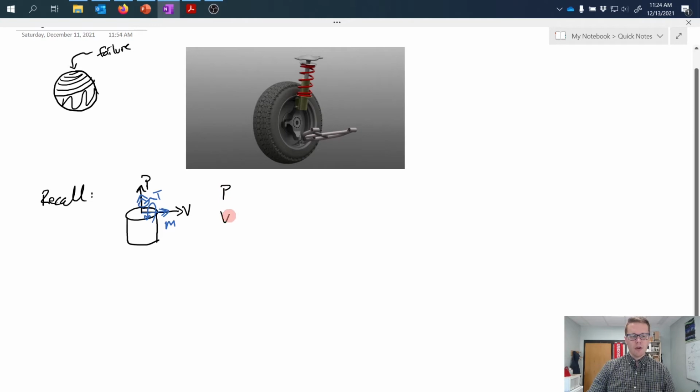So we take those and say, okay, we have axial, transverse shear, bending moment, and torsion. From those, we can compute some corresponding stresses. So we have axial normal stress, transverse shear stress, bending normal stress, and torsional shear stress. And we also have some relationships for those on the basis of the loading applied and some various pieces of geometry.